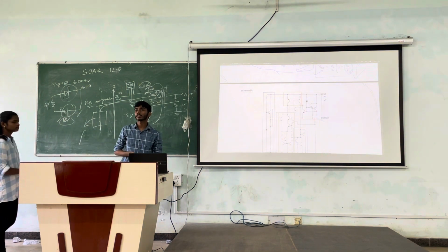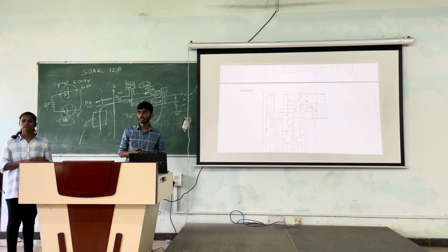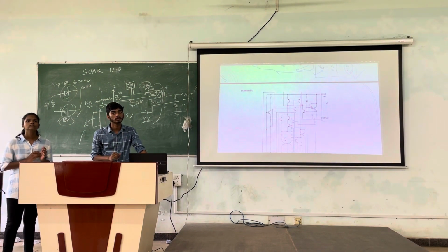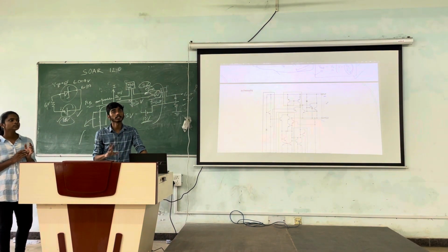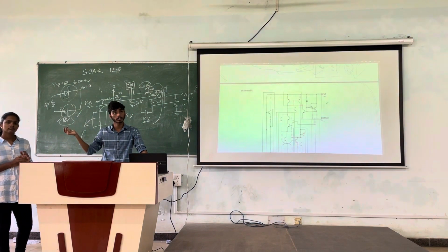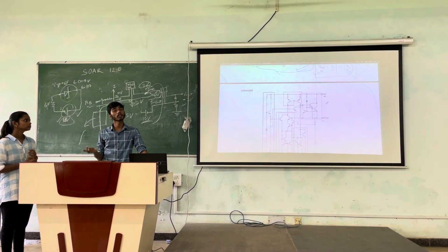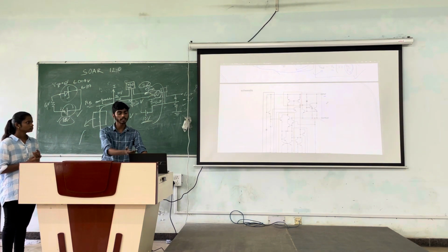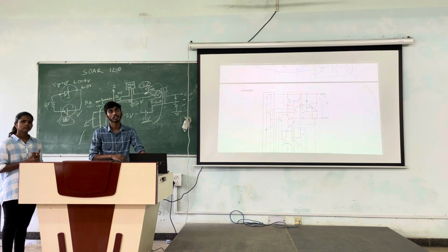Any word on voltage regulators other than 78 and 79? Basically, we are just discussing the 78 or 79 series here, or the LM317 variable voltage regulator. There might be some more voltage regulator ICs present in the market, but for our projects, we generally use this 78 or 79 series.